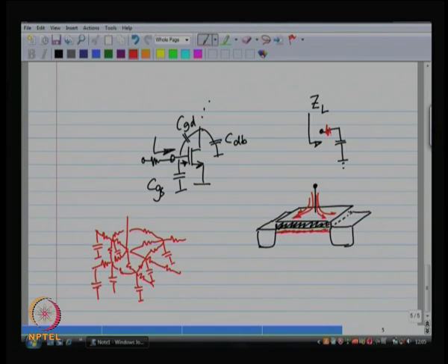So, it is a complicated model, and probably this distributed mesh of resistors and capacitors can be substituted by a model that looks like this, by a simple RC, where C is the capacitance of the gate to channel, Cox or CGS or whatever you want over there. And Rg is the gate resistance. So, this is the gate resistance that I am talking about. It is a distributed mesh of resistors all over the gate.